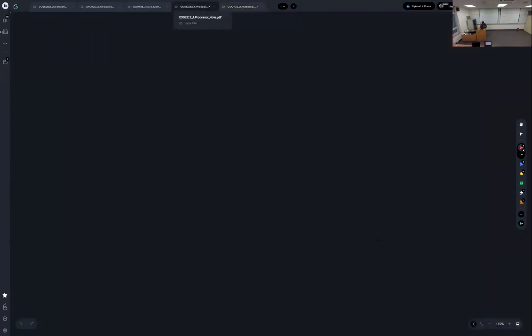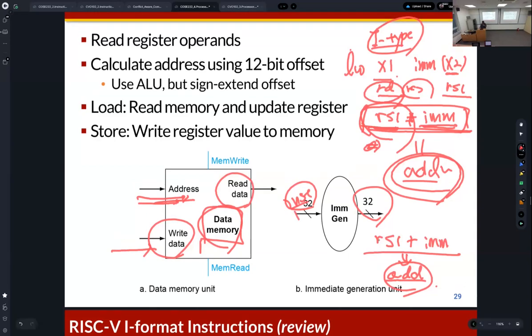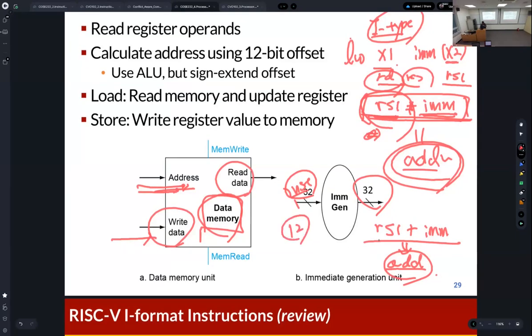So in order to simplify this operation, we just mentioned that the instruction is given, and then we generate the 32-bit immediate number because the immediate number is included in the instruction. Okay? So that's why it's 32. But actually, we just generate the 32-bit immediate number from the 12-bit immediate field in an instruction.